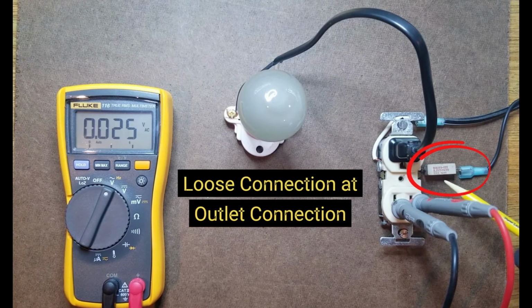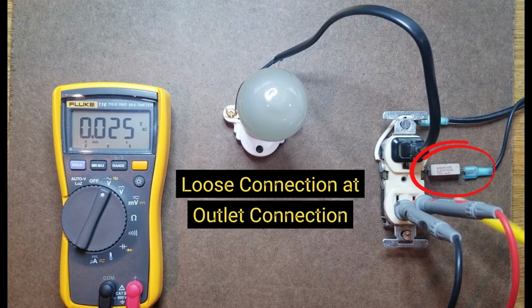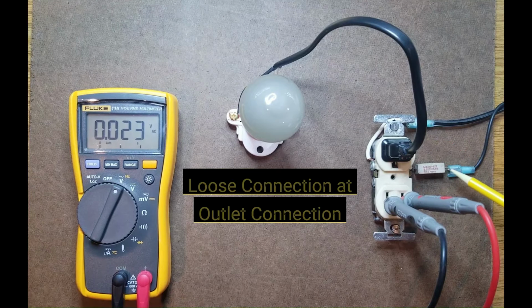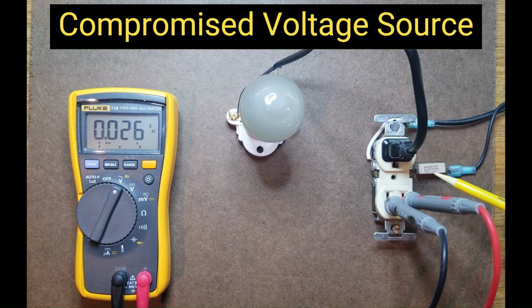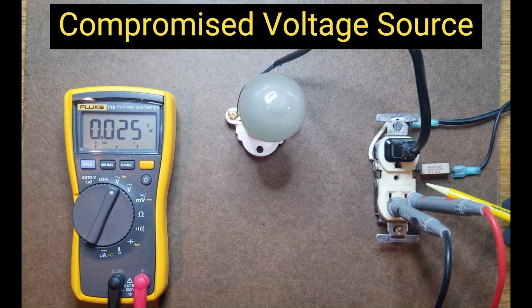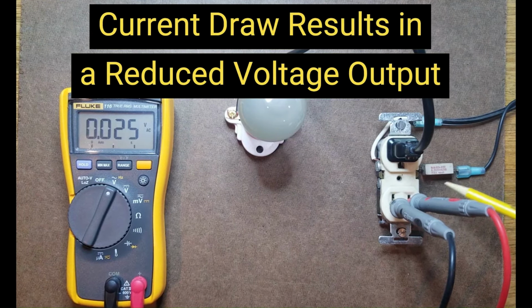However, what occurs when you have a solid voltage source, such as a 120 volt outlet, that has a loose connection where the wire attaches behind it? What if this loose connection has a resistance of a few thousand ohms? This can be called a compromised voltage source, because any attempt to draw current from it will result in a voltage drop across that loose connection.